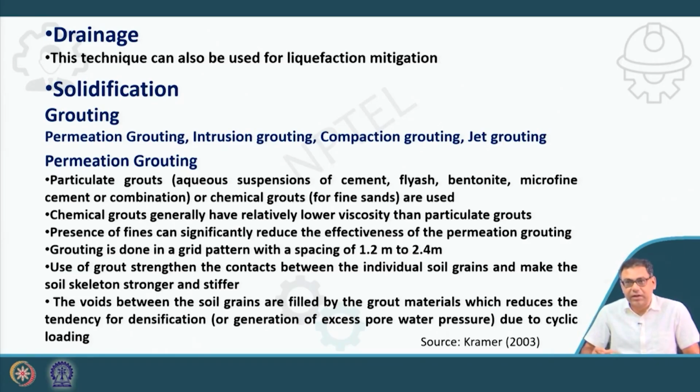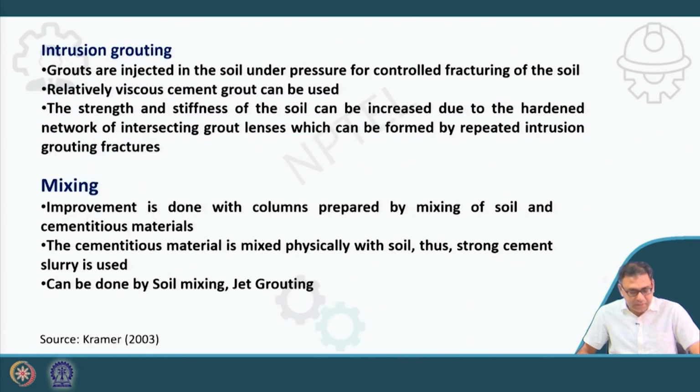and because of this densification, because when the seismic load is applied the soil densifies. And if the void amount is more, there is a possibility of generation of excess positive water pressure. Because the grout material fills this void, the possibility of generation of this excess water pressure is reduced. So this is permeation grouting.